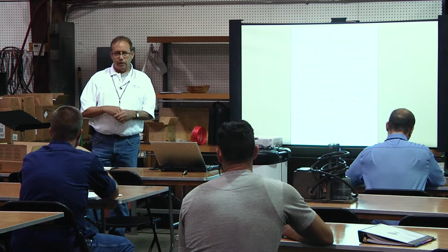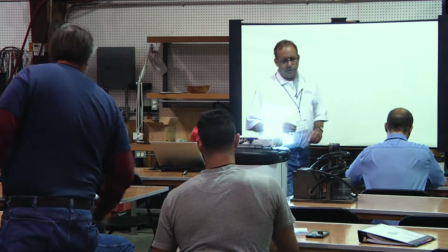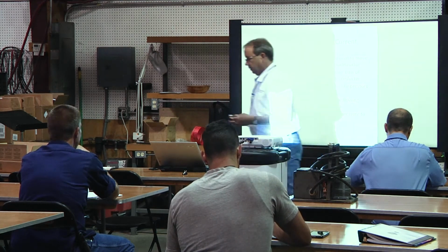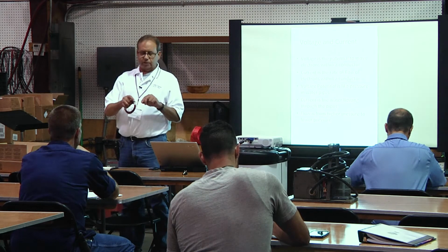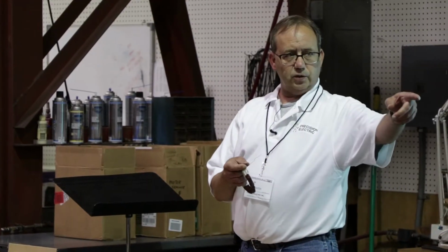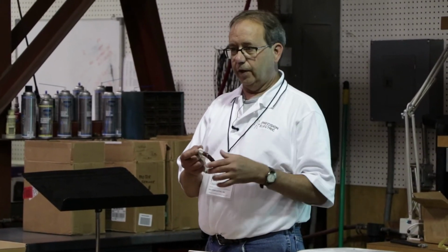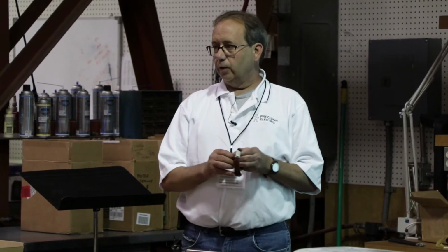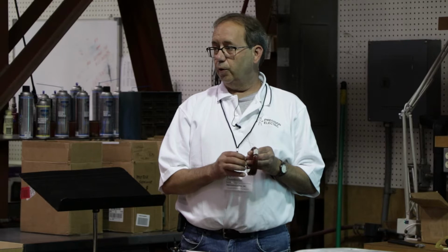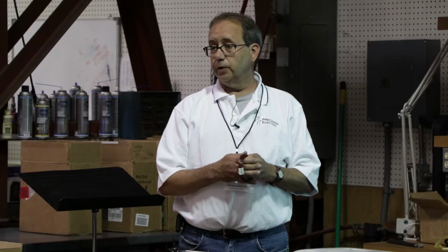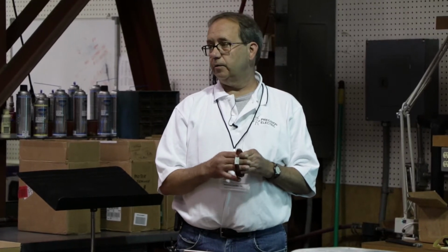Conductors are generally insulated. Like this is a coil of wire that we call magnet wire. It's copper wire, but it has an enamel coating on it, and it's the wire we use to wind motors with. If you look at this, each individual turn is insulated from the one adjacent to it. So if you get a break in the wire or a scratch in the enamel or you overheat the conductors, then you get a short in the winding and eventually a breakdown.